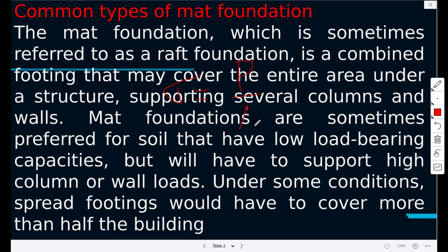So when you increase A, of course, when A goes up, then stress goes down, and that's what we need, because of course weak soils have lower Q ultimate, which is the bearing capacity. So that's the point.